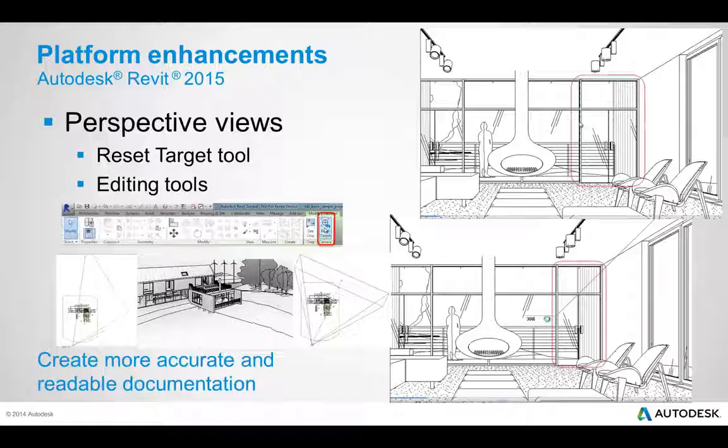All right, one that is specific to R2 and not Update Release 4, we're seeing it described that way: if we are a subscription customer, we should see functionality that now, inside of any 3D view, we should be able to right-click over the view cube and say, all right, let's make this a perspective view. We do this kind of thing if we utilize Navisworks. We can change from a parallel projection to a perspective projection.